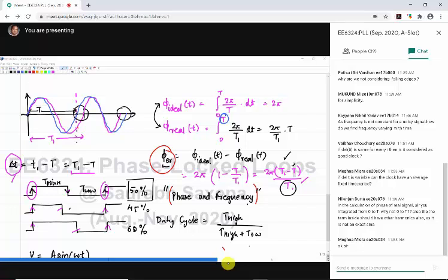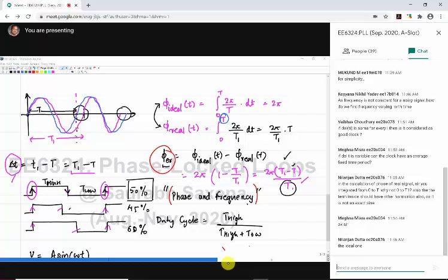In the calculation of phase of a real signal, you integrate it from 0 to t. Why not 0 to t1? Well, you can define with respect to t1, but let me ask you, with ideal and real clock, which can you treat as a reference? I do not know when t1 will come. T1 is a variable value. If you treat the ideal one as a reference, then I will find the phase error with respect to that.